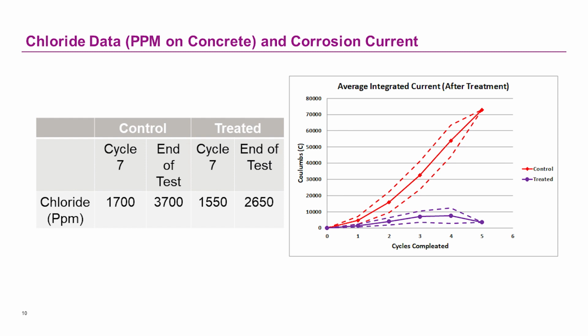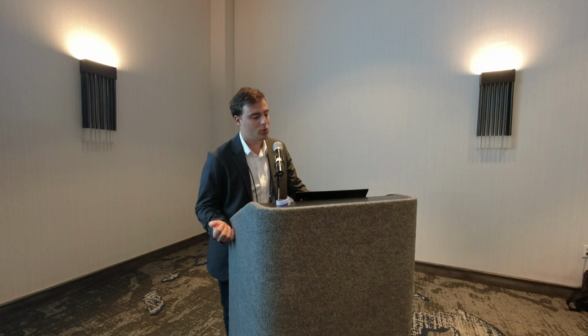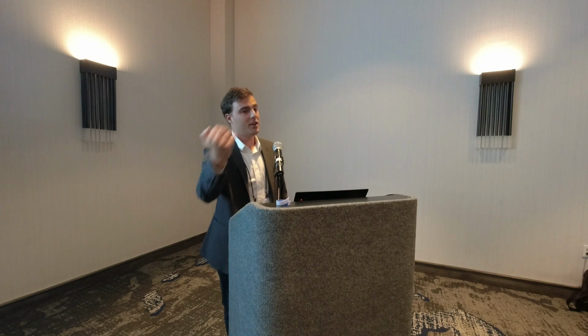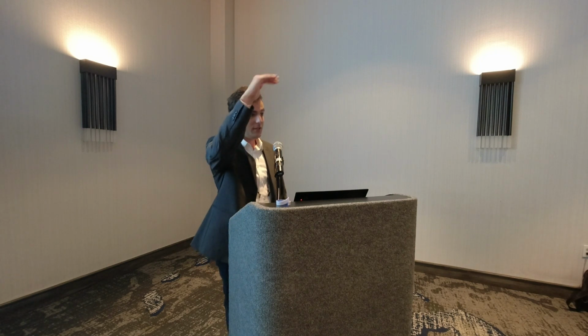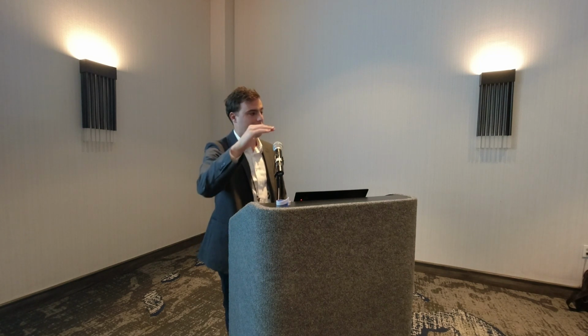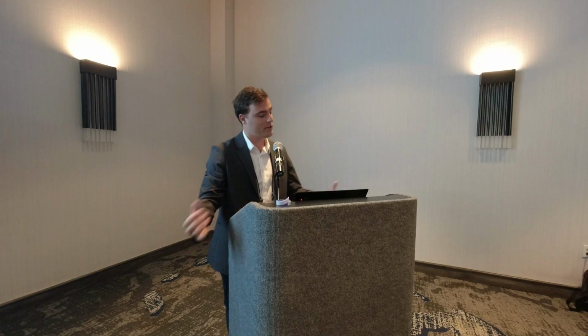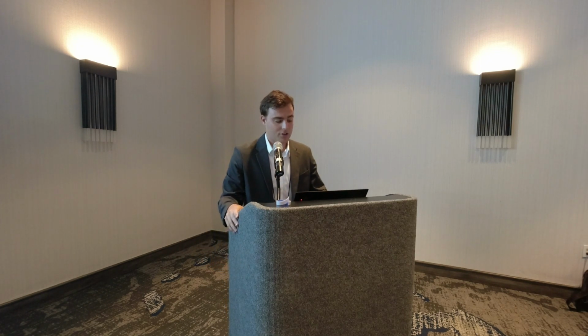And then you can see that even after a corrosion inhibitor is added, the chlorides do increase. That is mainly just due to the test being at 1.5 inches. You apply a silane to the top, you still have chlorides from the top of the slab down to the 1.5 inches, so they're still going to migrate down, but you can see there's a pretty significant reduction in chlorides.